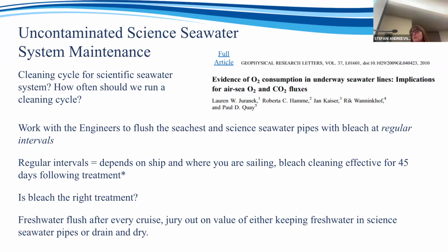And the other comment I have, yeah, we had some accidents with the impeller pump, so they burnt out, and it's usually the plastic part, and you can just buy the volutes and replace it, and it's much cheaper.